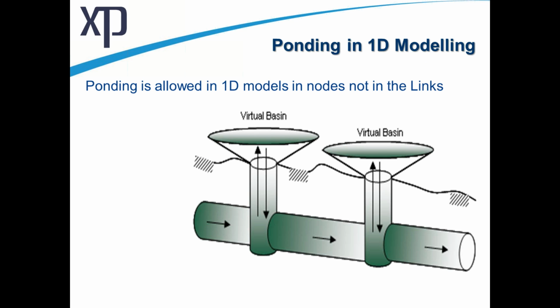1D models are very easy to troubleshoot. They need less time, less data, and less hardware equipment, and there is plenty of literature available for 1D modeling. However, 1D models cannot model the shallow overland flows correctly, as the flow pattern is essentially 2D. 1D models tend to overestimate the water depth and velocity due to the 1D assumption.